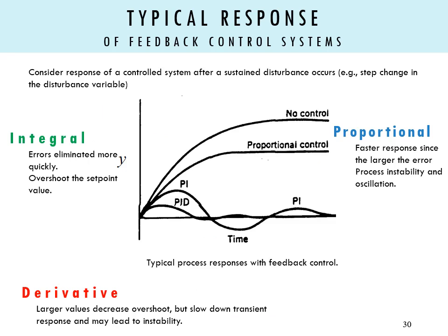Every P, I and D term has a different effect on the output response of the PID controller. In any disturbance and step input change event, the output response of a process without a controller is shown in this figure. The output response behaves moving further away from the set point with no sign of approaching the set point, which we try to avoid in any process. The output response with the proportional term, known as the proportional controller, however, improves by approaching the set point.